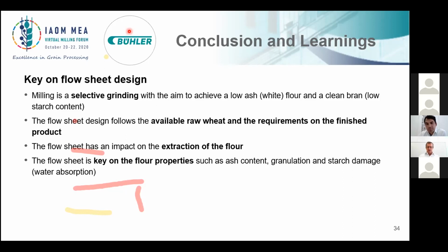So it all starts with, let's call it, the protein content, hard, semi-hard. When you talk about the semi-hard, it can be 11.5, 12, 12.5, a hard can be 13 and higher. If the difference is too much on the protein, meaning also the hardness, we should condition it separately, and then you can still blend it before first break.